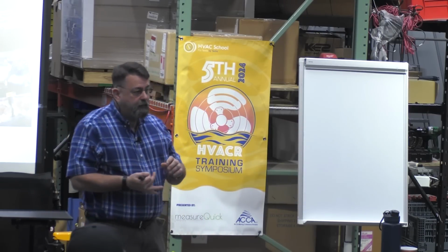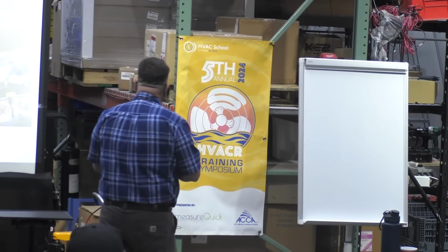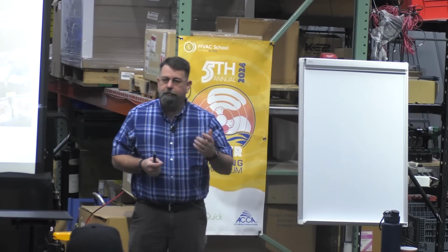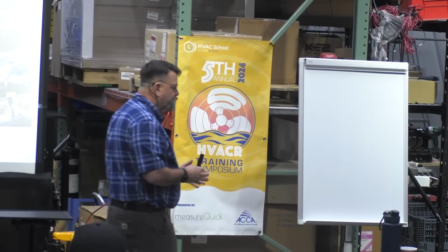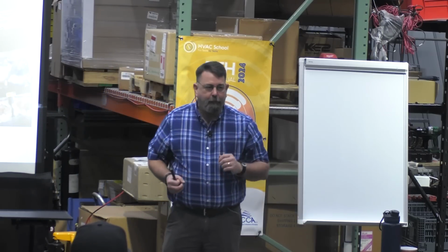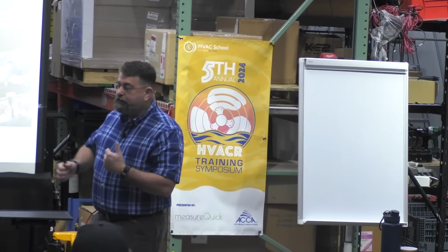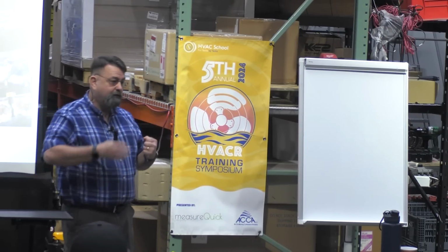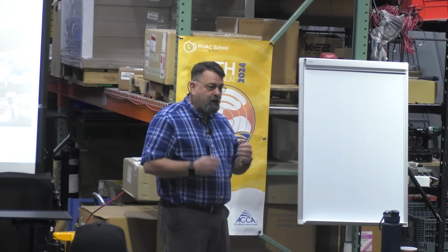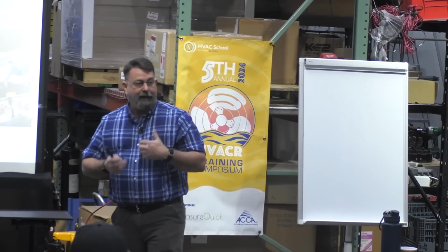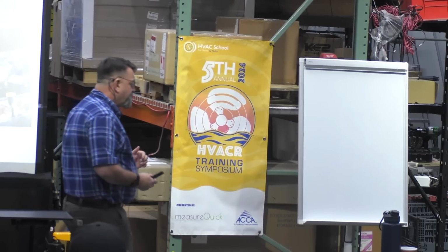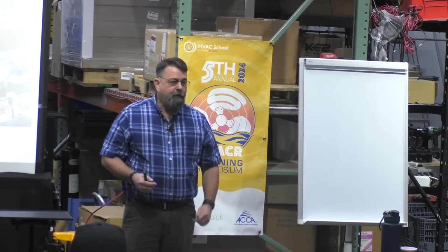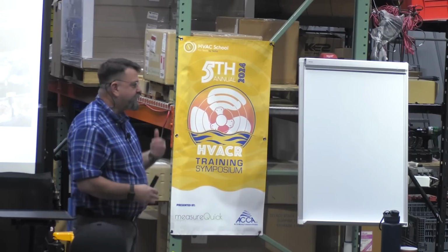Get into commercial and then try to get some exposure to some restaurants, some convenience stores, right? They have small refrigeration. It's really simple stuff. 1 compressor, 1 evaporator, right? And use that concept that I was just giving you about the suction pressure equals my boiling temp. Nail that down. Get that nice and solid. You'll start seeing some liquid receivers on those setups too. And so you'll see critical charge no longer applies, right? How do I control this? How do I control that?